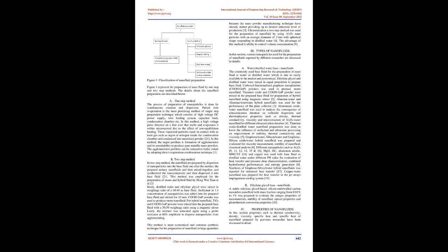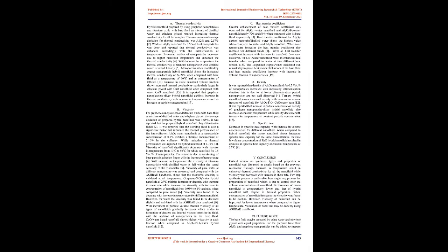6. Different nanoparticles such as Al2O3 9, 11, 12, 14, 15, and 16, MgO, SiC, aluminum nitride, MWCNT 18 and copper were used with base fluid as distilled water under different pH values for evaluation of heat transfer and pressure drop characterization, combined hydrothermal performances and entropy generation. 8. Synthesis of graphene silver/water hybrid nanofluids was reported for enhanced heat transfer. 17. Copper water nanofluid was prepared for heat transfer in the jet array's impingement cooling system.